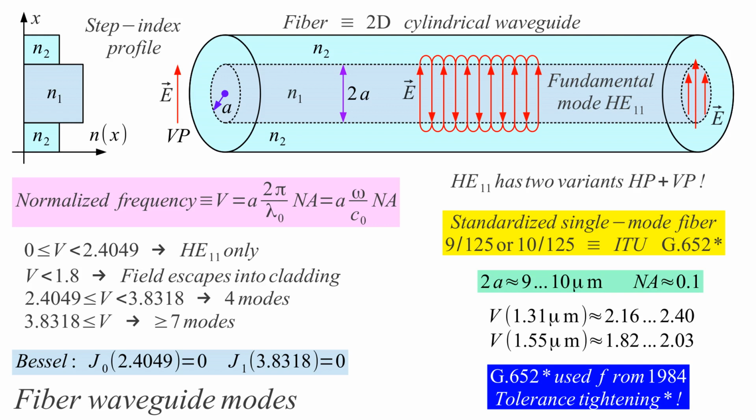Single mode fiber was one of the first low loss fibers. But the problem here is the core diameter of only 9 micrometers. If we have just 9 micrometers of core diameter, we have to have very accurate mechanical connectors, very accurate arc welders to splice these fibers together.